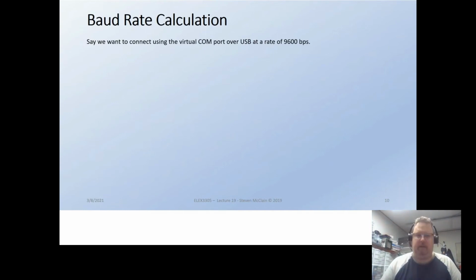And then the other one is a user COM port. And that user COM port is hooked up to the UART. And if you look at the schematic, you can figure out which UART, which pins, and all that stuff. In the middle, you have a whole row of jumpers that are all stuck together. Those are jumpers for power, and some of those are connections for the debugger. And a couple of those you'll see, well, I don't actually have the real board here. Basically, it'll say TXD and RXD on this one. Probably the same on that one too.